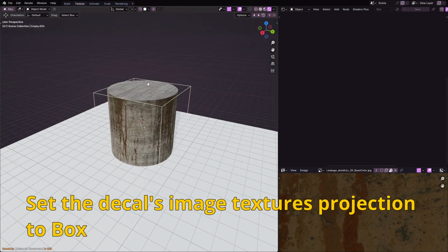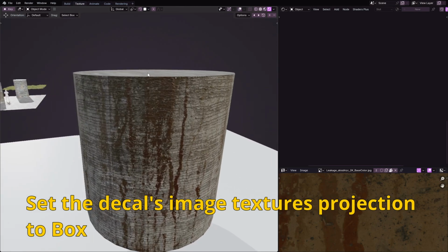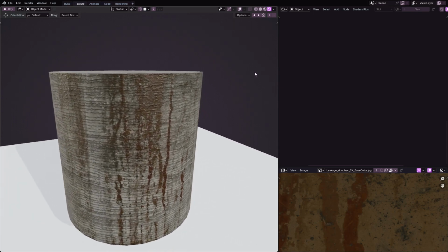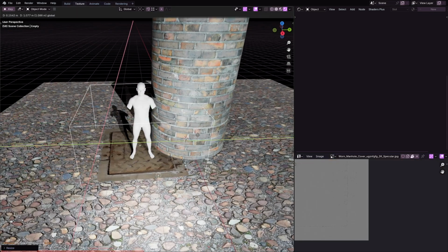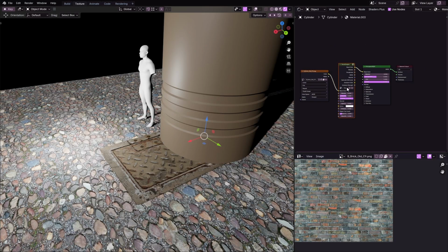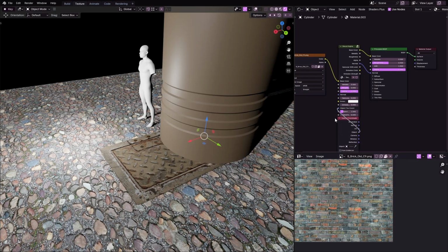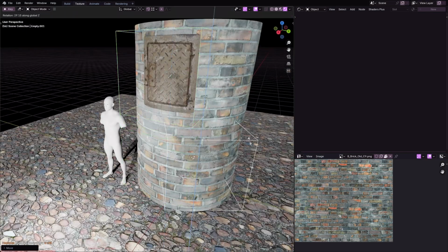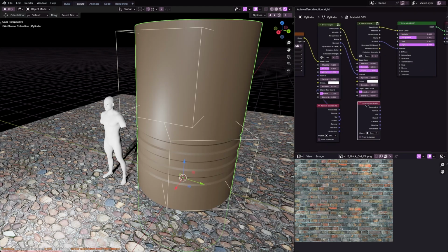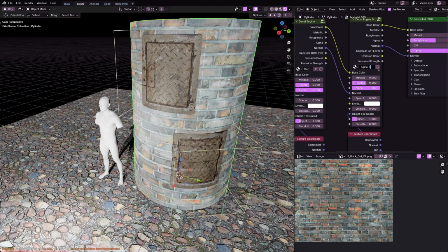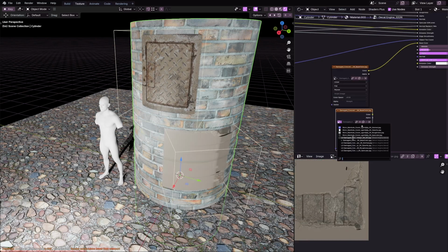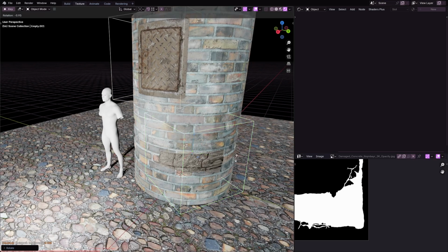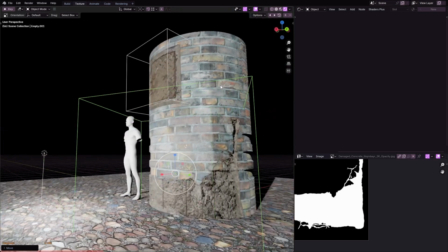Expand your knowledge, expand your tools. The decal will only appear on the materials you want. Want to see it on other materials? Simply copy the top-level Decal Engine group node and insert it into the material. You're not limited to just one decal per material either. Simply add another Decal Engine node to the same material, link it up, and configure it as before. Give it some different textures and its own cube empty, and layer your decals like a pro!